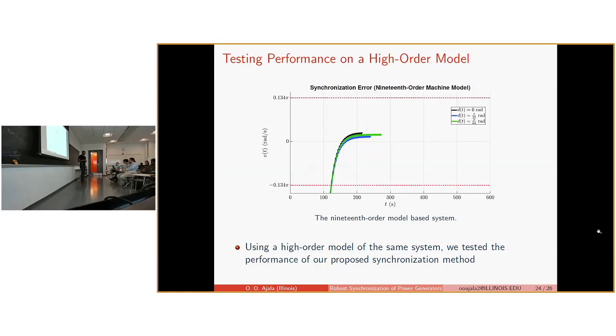I guess that might be something worth looking into, but my guess would be that if we can get multiple PMU measurements, we can interpolate and see how fast the phase is increasing, and then try to match the phase of the follower to that. So if there was going to be a delay, we would extrapolate based on the measurements we currently have.